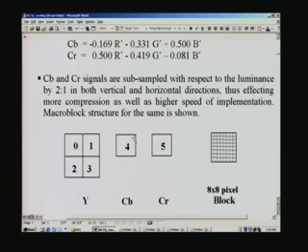So in order to contain this, the trick played by and recommended by the standards is this. We have also already seen that our eyes are sensitive only to luminance and not to the chrominance. A color component, you can easily fool our eyes by taking only alternate pixel color and processing them. So for example, in this block, take the first pixel, then the third pixel, then the fifth pixel and arrange them. If you take the total macro block which will contain 16 by 16 pixels, you will extract only an 8 by 8 block. So that is what is shown here.